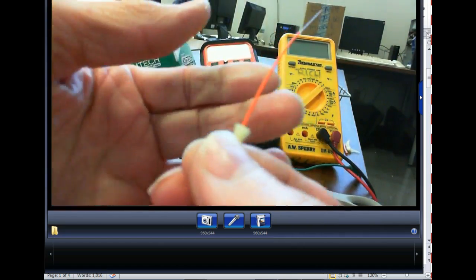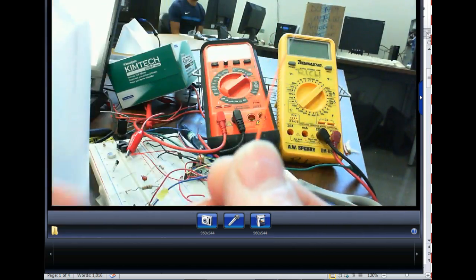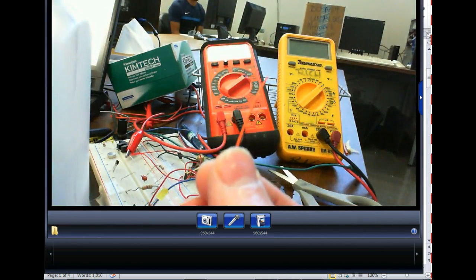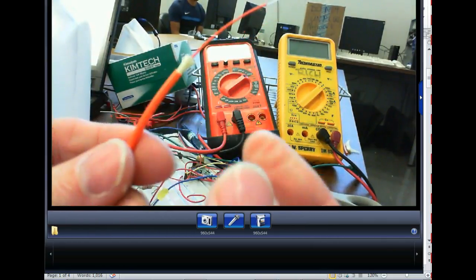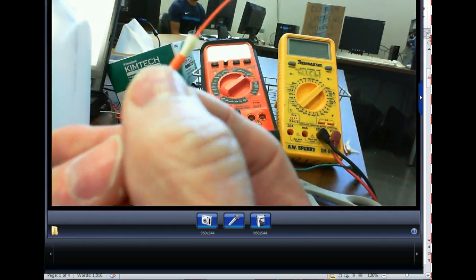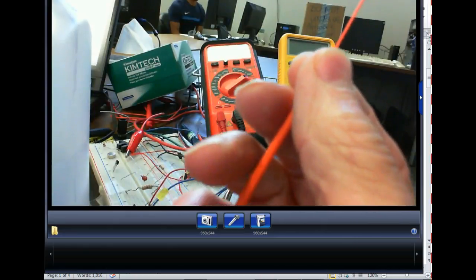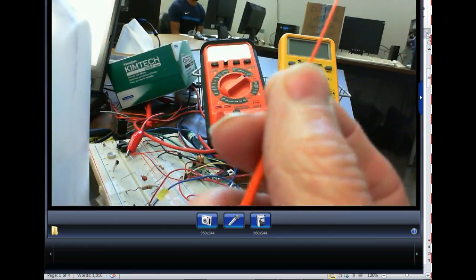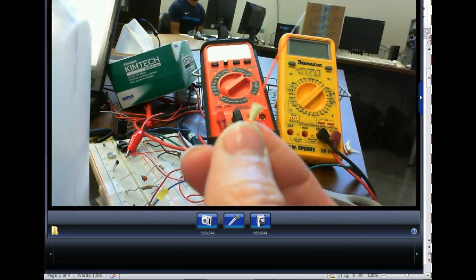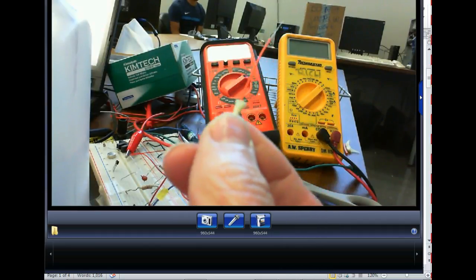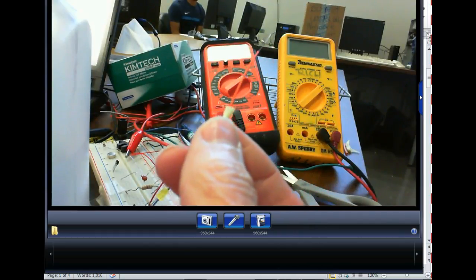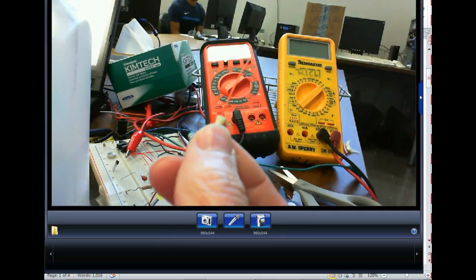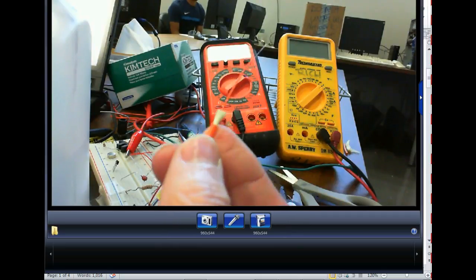Mostly on splices, we crimp down on this one, but then we put it in a protector we call a splice tray. Your connectors are going to crimp onto this outside jacket and the Kevlar. And if you don't have it cut right and you get it down in that connector and then you try to get it out because you cut it too long or too short, then odds are the glass is going to break, right?